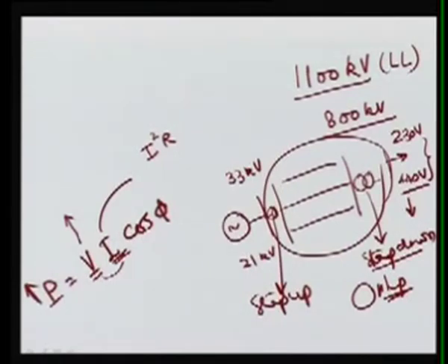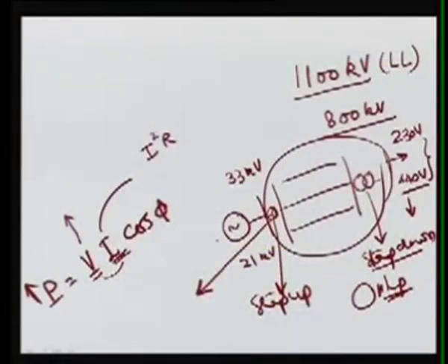Normally the transformers near the generating station are step up, and the other transformers near the end users are step down transformers. However, we also use some other transformers. The transformer used near the generating station is called the GT, generating station transformer. If you are using it at the distribution level, then it is called DT, the distribution transformer.